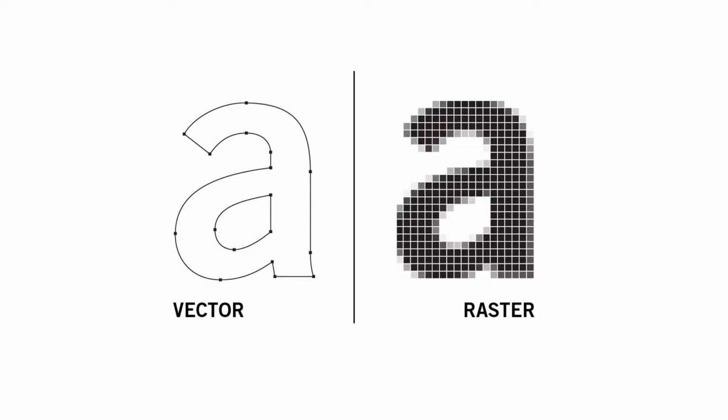This creates a numerical map for CNC software to plot the direction of travel for your machine tool, and anything that interferes with this map, such as another vector crossing its path or a break in what's intended to be a complete contour, can interfere with the way the software interprets the vectors for toolpathing. It's also useful to know that the reason you can't use bitmap raster graphics to create toolpaths is because it's essentially colour information laid out in a pixel grid, and they lack the coordinates required to create this map.